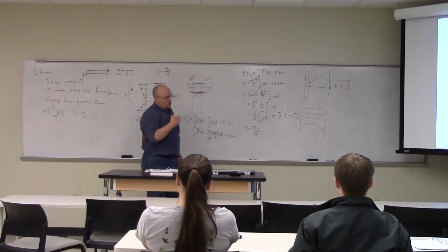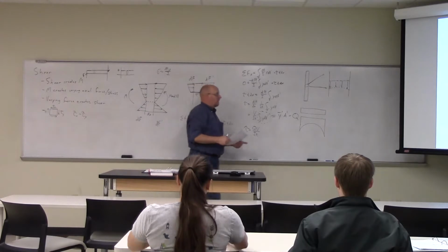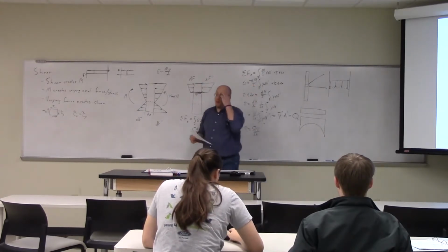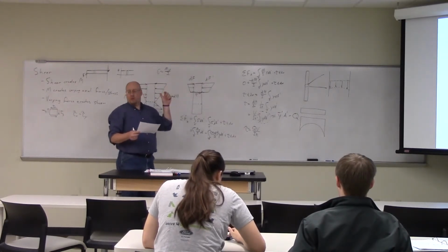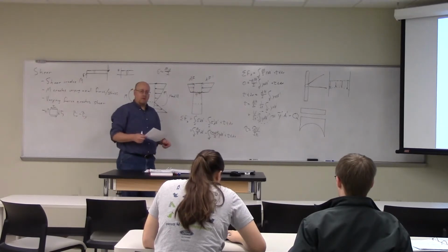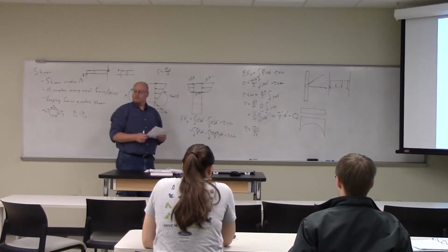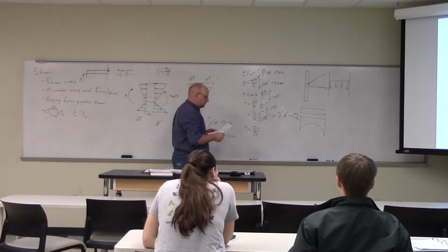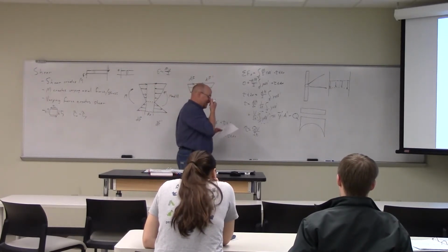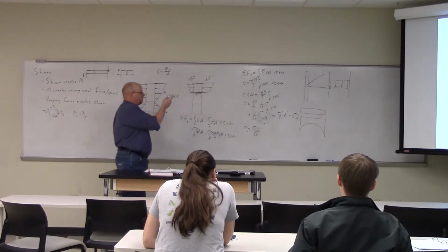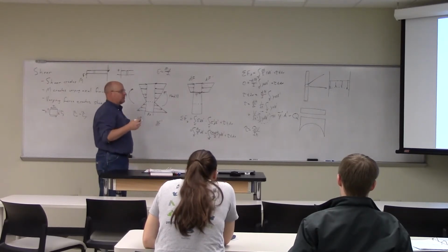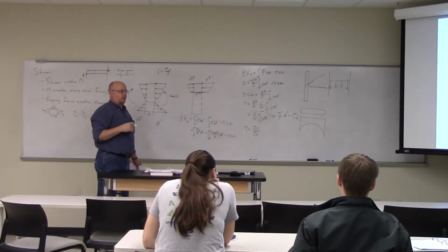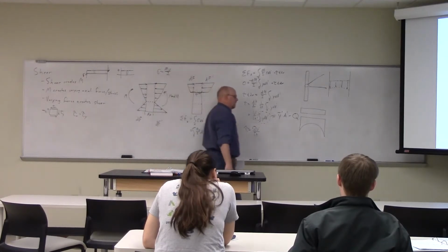Okay, so the shear stress across the z dimension can vary significantly if that member is wider than it is high. But as long as the height is roughly 2 times the width, we don't have to really worry about it. Okay. Also, this whole analysis only works if the line that we're calculating shear stress for is perpendicular to the surface.